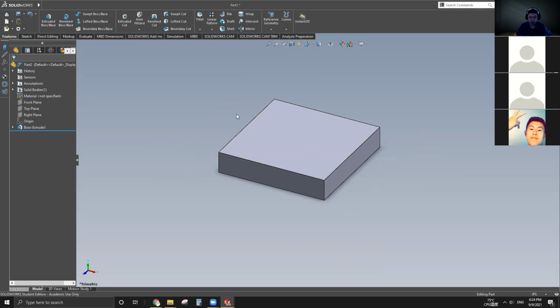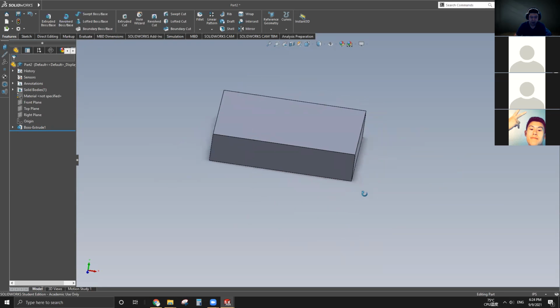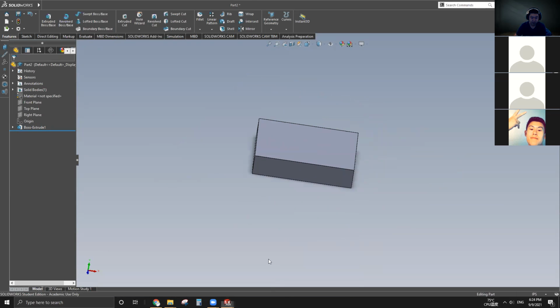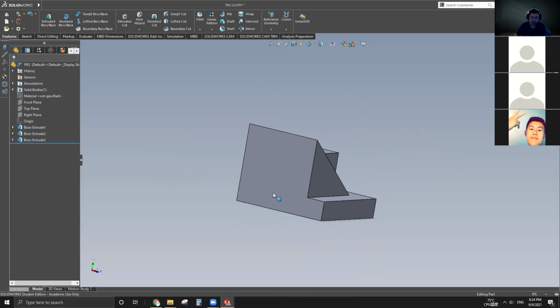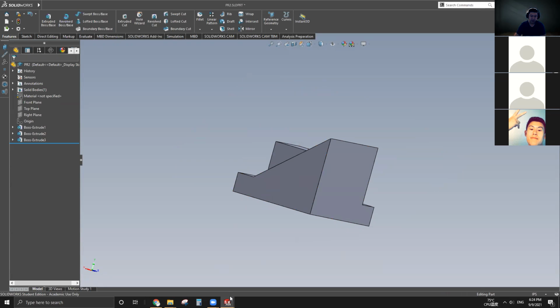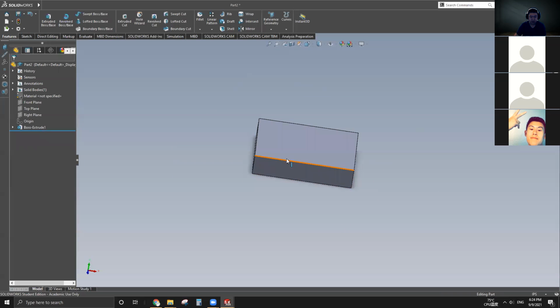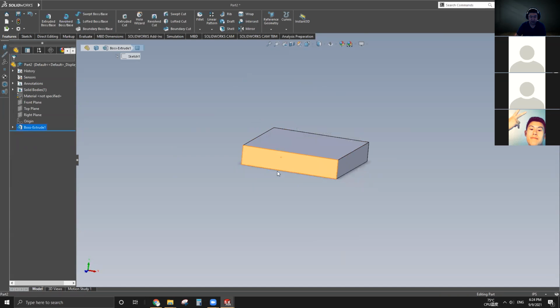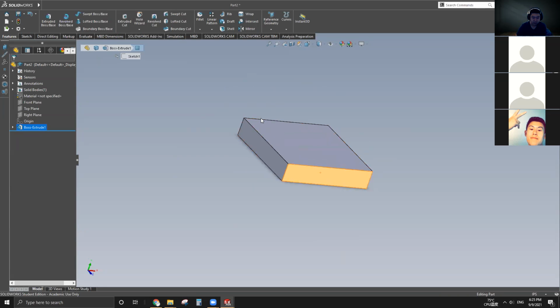And let's build the triangular shape on top of it. And we know the triangular shape from this view, from this model, is sharing the plane of this side of the plate and also this side of plate. So we can treat this side as the back and start making a triangular geometry right here, and extrude it to a certain distance that is not going too much to this edge or even going over this edge.